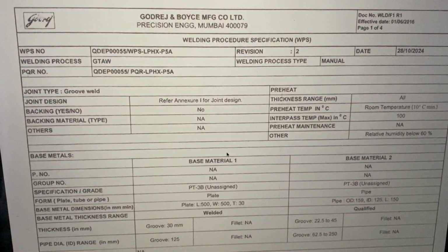So to do that, let us first understand what a welding procedure specification is. It is more like, in the PDCA cycle, our plan as to how we will be executing a given joint: what consumables, what parameters, what kind of edge preparation, how we are going to use them, what the essential variables are as per code, and how we are going to really achieve a successful joint. So it is a planning sheet which is prepared by a welding engineer. First he has to understand what the material is which we are going to weld.